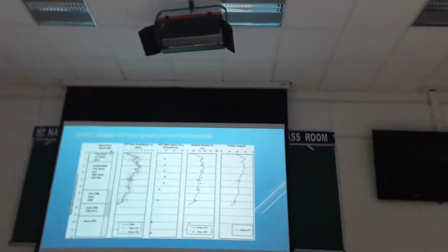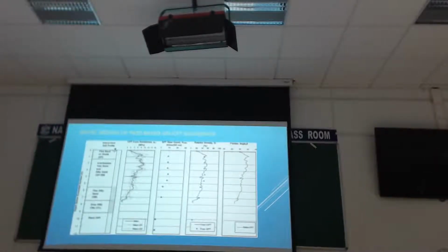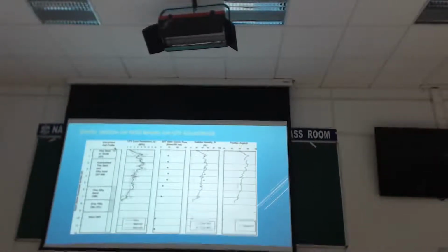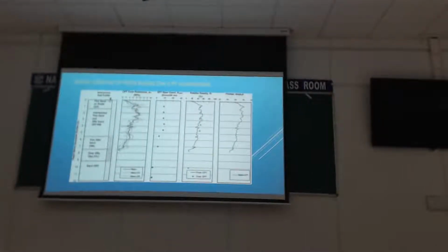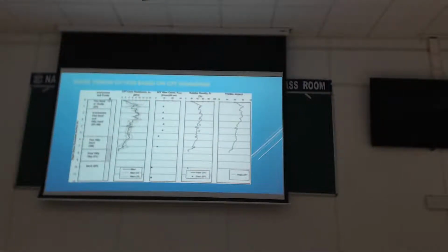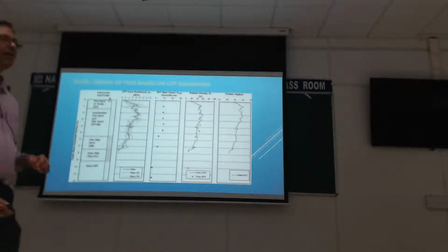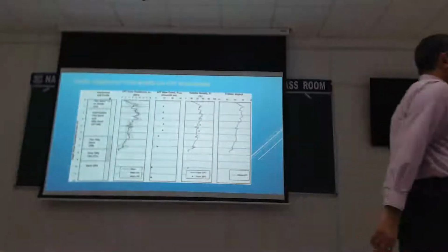Depending on your cone, you can also get a water pressure measurement, so you call them piezocones, and you can get a measure of the sleeve resistance as well. So you can identify the difference between the cone tip resistance and the shaft friction. And they do that by having two parts to the cone.